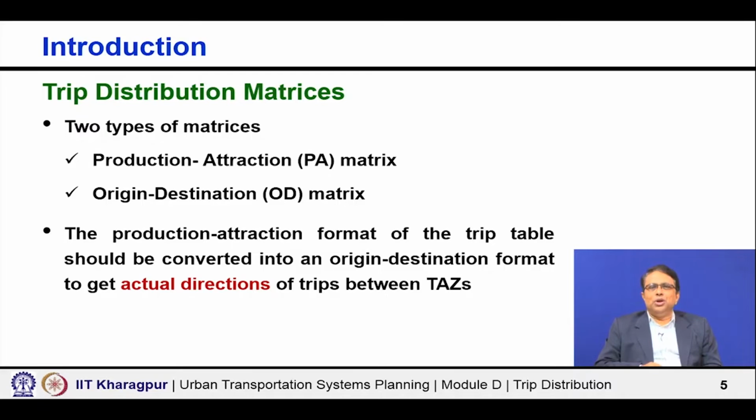So, I want to know from zone 1 to zone 2, that means from home to office and office to home, the direction is important, because of your mode choice. When you want to understand in the peak hour how many people would like to travel in one direction, because in terms of actual travel the direction is very important. So, you would like to show in the peak hour, in the peak direction, how many people are trying to travel, and therefore, how many buses will be required to serve the demand with a desired level of service maybe.